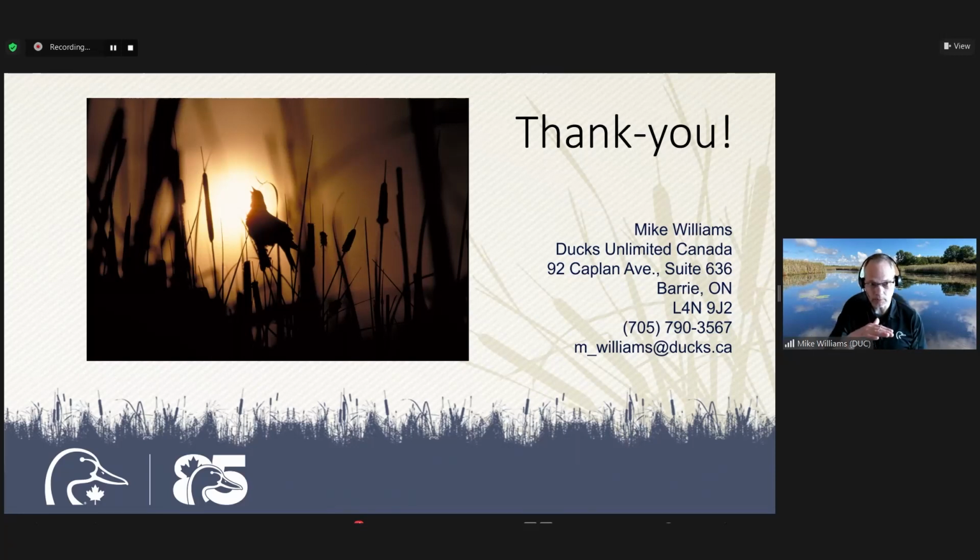It's true the ponds are only going to be about a foot deep to support the cattail ecosystem, but at either end of the surface water management ponds and the polishing wetland, we have these deeper cross ditches, not only to function to spread the water out evenly through the cattail, but they will also serve to drop out any sediment, sand, whatever is being carried into there. And again, the water coming from the wastewater treatment plant won't have any sediment in it. There could be some sediment coming in from the sides, but if it does tend to settle out, it will be in those cross ditches. And those are the areas that could be cleaned out, and it wouldn't affect the cattail community at all.